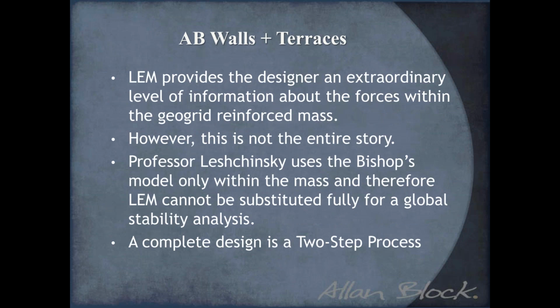So to sum things up a little bit, that LEM provides the designer an extraordinary level of information. Every inch or so on any grid of any wall, you're going to have a T required available, and you're going to be able to determine those T maxes. So it's a wealth of information within the wall design. That's what global stability brings to the system. We can use thousands of slip arcs to determine these forces. But it's not the entire story.